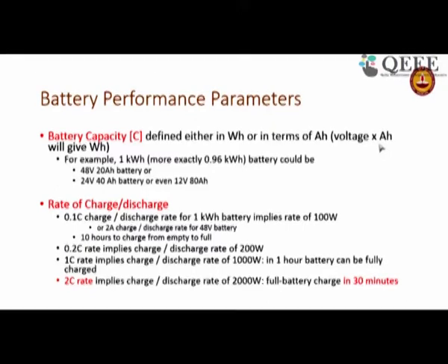Now this is extremely important. For example, suppose I am driving an electric car. I am going to get an electric car next week. I am going to drive, and all of you are welcome. I will drive you. If my battery becomes totally zero, the car stops. If I charge it at 2 C, in half an hour it is fully charged. But if I charge it at 0.1 C, I will require 10 hours.